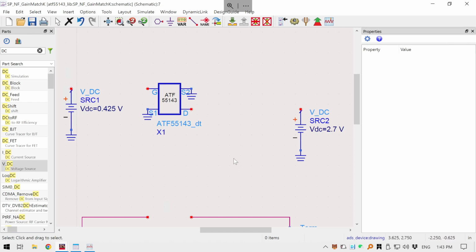And for your amplifier circuits, you will notice that the fabricated circuit will not always follow the same biasing. So in that case, you need to give a VDC voltage to your amplifier, and you need to tune the gate voltage so that it will have the same current as your design and also the datasheet.